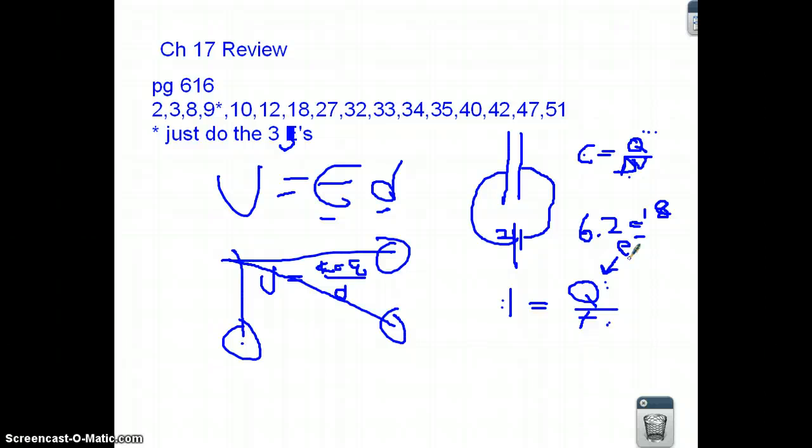35. Each of the wires shown is made of copper, and assuming each piece of wire is the same temperature, which has the greatest resistance? Looking at the three pieces there, the two wide ones, A and D, would not be the greatest resistance. So the greatest resistance would be C. It is both narrow and long. The least resistance would be between options A and D, D being wide and long. Long is not good for resistance, but wide and short in number A is going to be your least resistance.